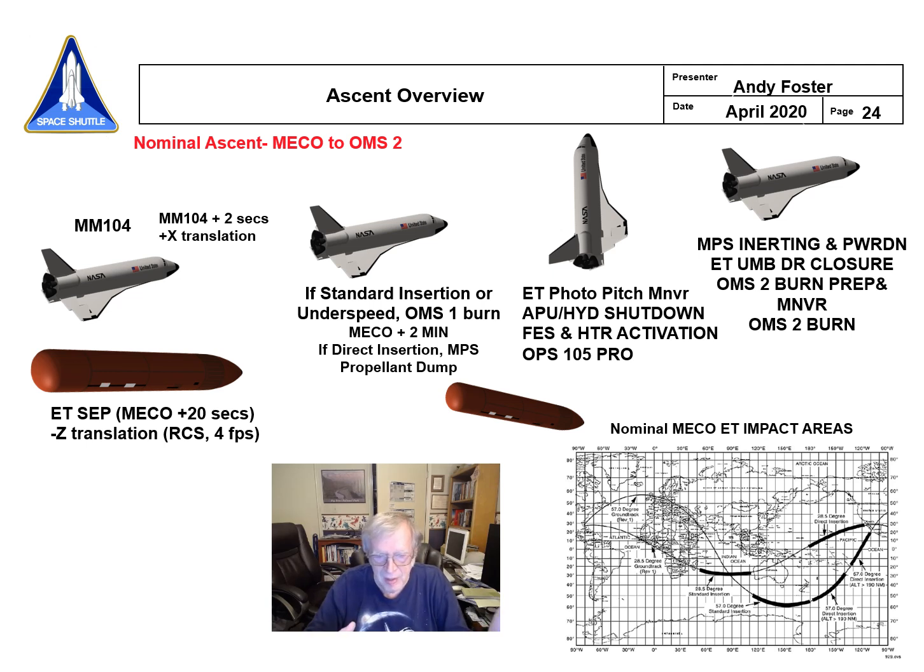We're going to try to get it off, essentially to help us with maintenance later on and turnaround, that kind of thing. And actually, you dump LO2 out the bells and LH2 out the side through a dump valve, and the LO2 actually would give you a little bit of thrust as it went out the back end.